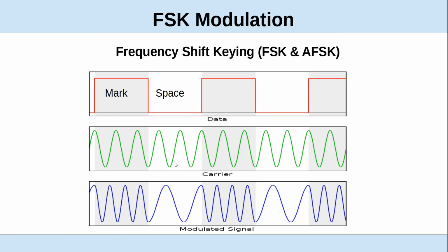I don't remember the frequencies right now, but for some of the simpler FSK modes, there's two different ones. 1,000 hertz and 1,500 hertz are pretty common. Okay. Center frequencies. So you're just shifting that in order to convey a 1 or a 0, what they call a mark or space. Another test question.